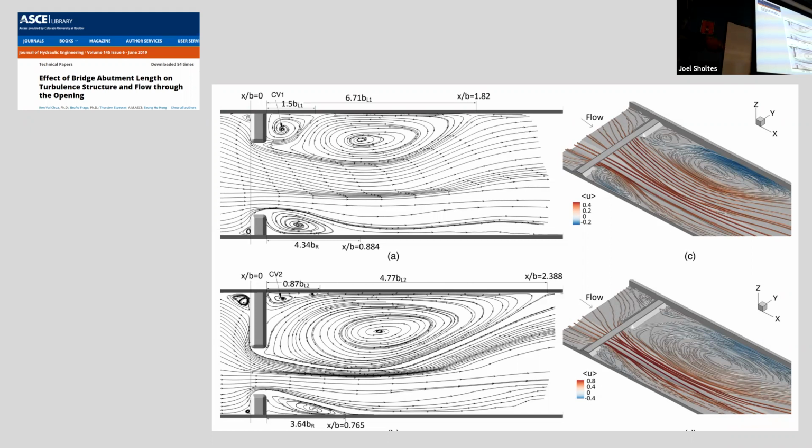So here are flow lines that this model is tracking in two and probably three dimensions. And you can track where you would get scour, elevated velocities, or you might get deposition in these eddies downstream. So this is really cool and helpful because you can build this model relatively inexpensively and do a bunch of scenarios to figure out how configurations of abutments are going to impact flow and sediment transport through this bridge span. Obviously, it's cheaper to do this than to build it and have it not work out, right?